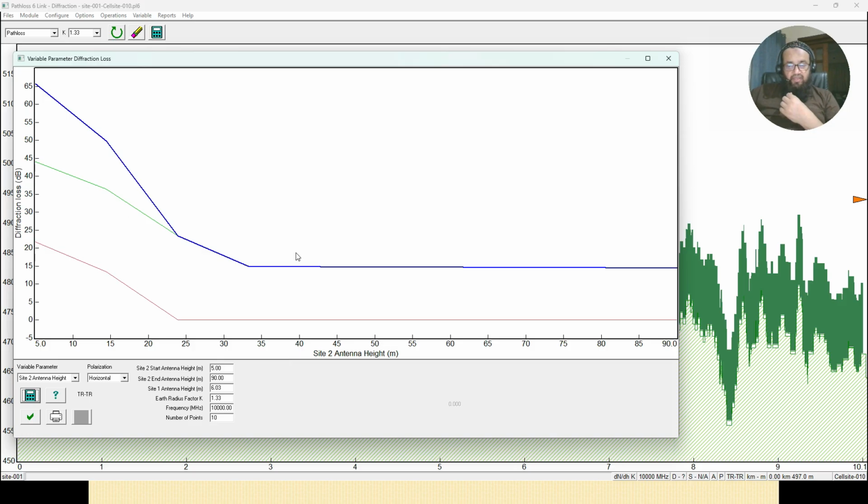This green is basically because of this vegetation. So this green has added almost 45 dB extra diffraction. So your diffraction starts from 65 dB now. You will have 65 dB attenuation at this point, and it will go to around 34-35 meter, and then it will be flat up to 90 meter, I mean, and the flatness is also almost 17-18 dB or 15 dB.